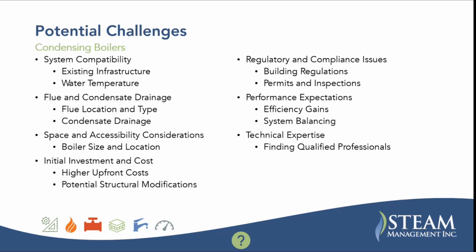And then you have regulatory and compliance issues, performance expectations. You've got to make sure that your process is actually going to perform in a way to really get the benefit of the condensing boiler. Like we mentioned, if you don't have a low enough hot water return temperature, you're not going to get the full benefit of that condensate in the flue gas.